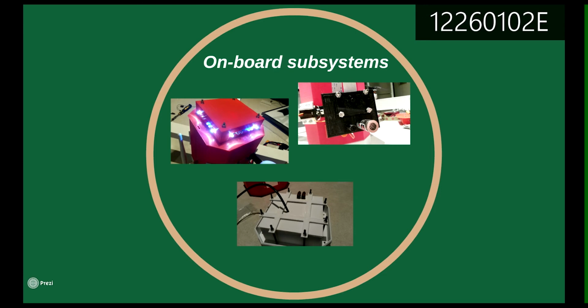The onboard video camera is coupled with the Raspberry Pi and sends a live video feed to the computer base station at a resolution of 360p. It can also capture high-resolution still images. The emergency lighting system was a last-minute addition. This was because I had to split the Arduino control circuit into two parts due to a lack of I/O. It features red and blue flashing lights and white headlights, which can be dimmed to mimic high and low beam. A piezo buzzer is also included to simulate a police siren.